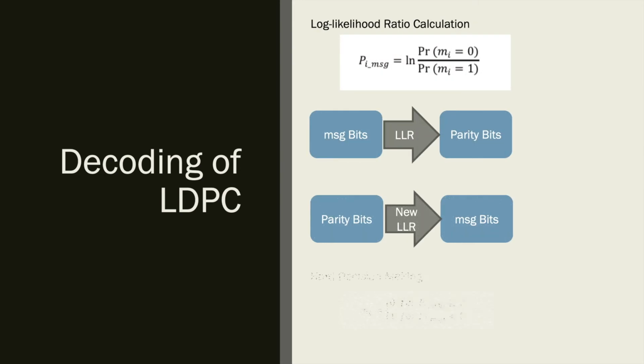The main idea of this algorithm is to use the log likelihood ratio as input, passing this information between parity nodes and message nodes, and obtaining and storing the new information by calculations based on the previously received information. This process is repeated iteratively until the maximum number of iterations is reached. Then apply a hard decision, or shall we say the normalized estimation of all of the information of each node, compare with the threshold and produce the output.